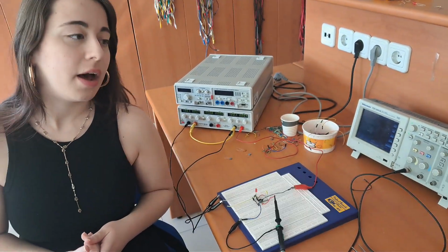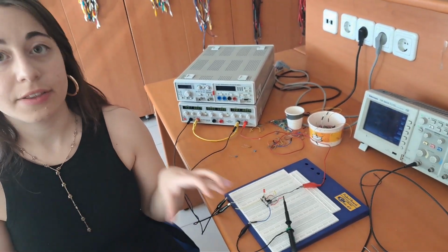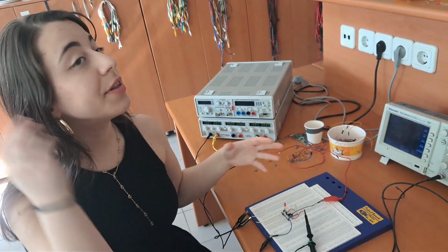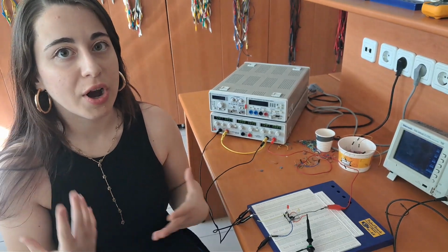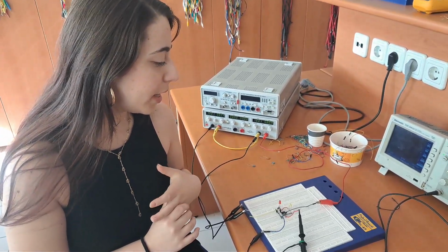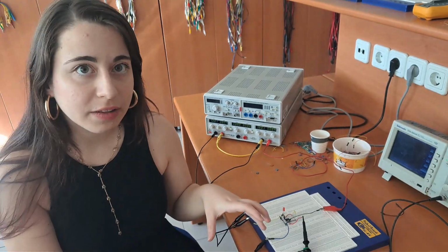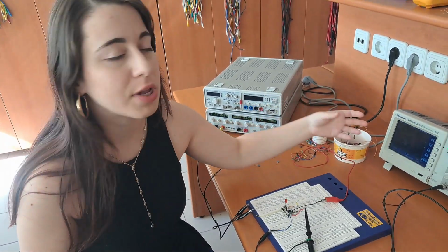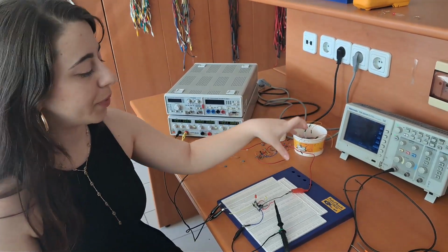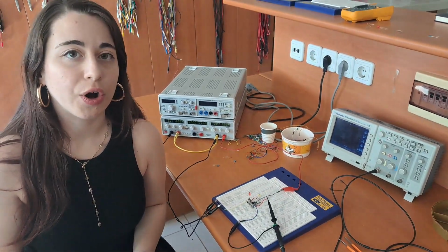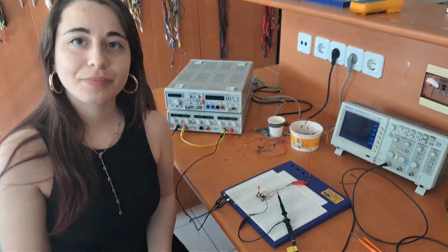Now I will explain the second part of this project. Here, instead of a resistor in the feedback loop, we use a capacitor, making this circuit an integrator. The purpose is to let the current accumulate on the capacitor so that we can measure small currents more efficiently. Here, also, we don't use a multimeter to measure the output voltage anymore. We use an oscilloscope so we can see the ramp and calculate the slope and multiply it with the capacitance to calculate our photodiode current.